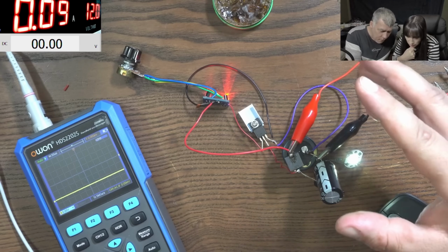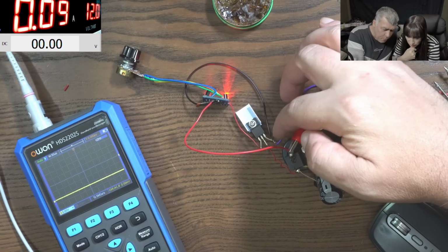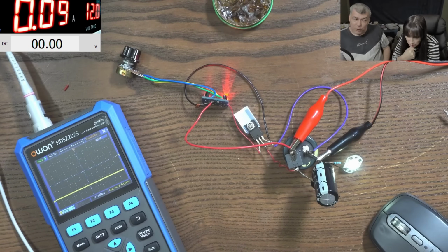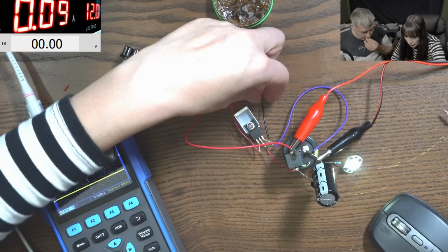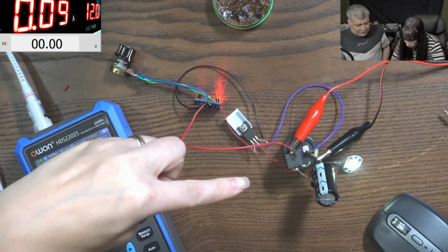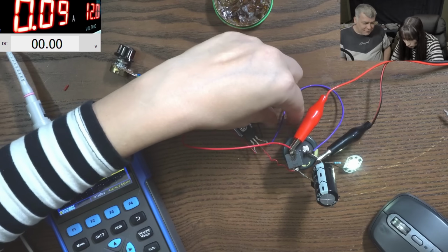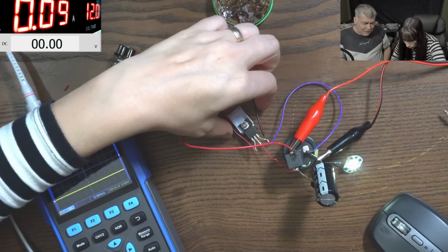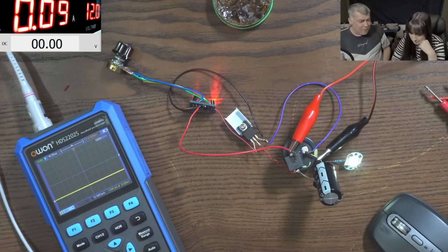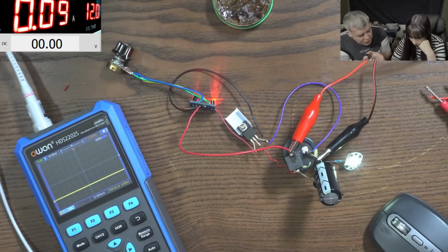Or you can leave the wire there, but you have to connect this pin exactly on the minus of the capacitor with no wires. So either you take the black one and you connect it there, try it, or you get rid of this purple and connect straight to the minus. Exactly. Because they have to meet exactly on the same point, and the point is exactly on the capacitor.